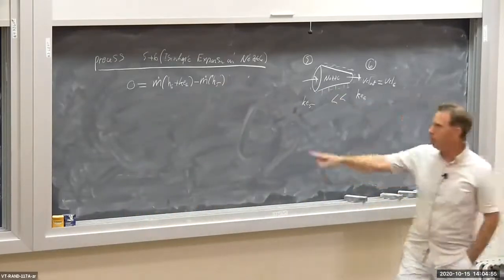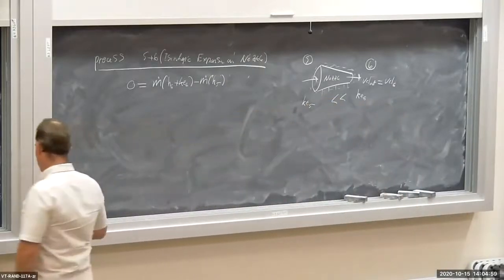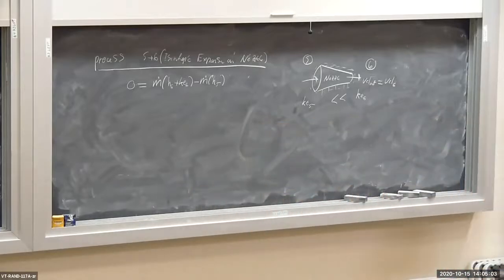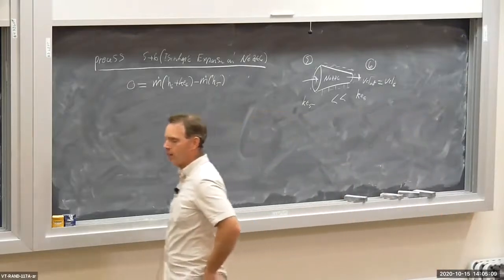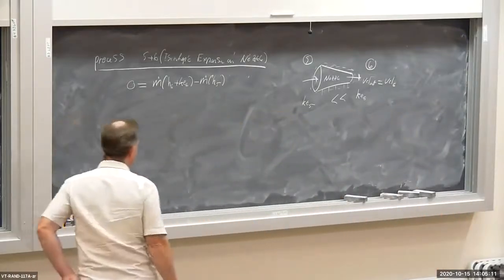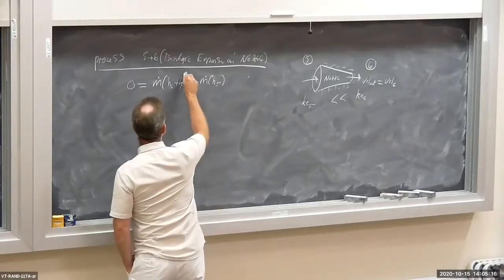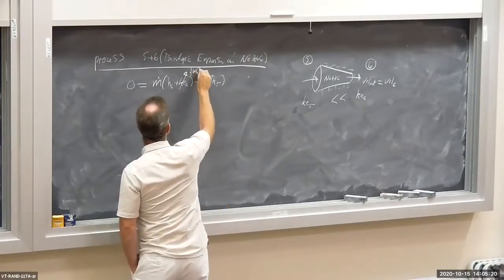So that's why we're missing the kinetic energy term at the inlet, okay? On these nozzle and diffuser problems, you should neglect the kinetic energy somewhere. For the diffuser, you should neglect the kinetic energy at the outlet. For the nozzle, you should neglect the kinetic energy at the inlet. Now, of course, ke6 is 1/2 velocity 6 squared.